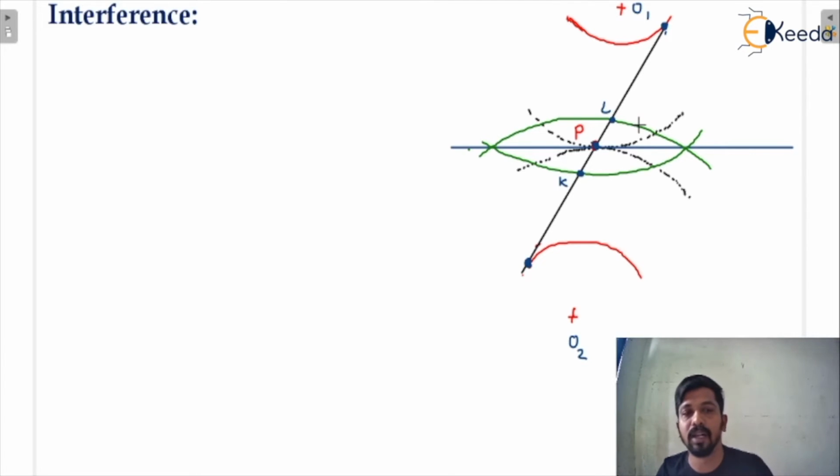See, we are going to understand interference using the diagram. See here, there are circles. The black dotted line shows the pitch circle for the gear and the pinion. This is the gear and this is the pinion. The red line represents the base circle for gear and pinion, and the green line represents the addendum circle for gear and pinion.